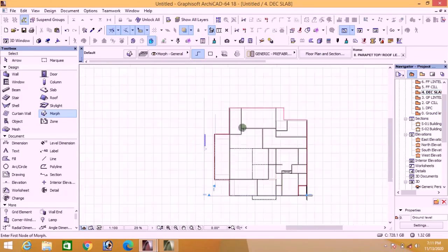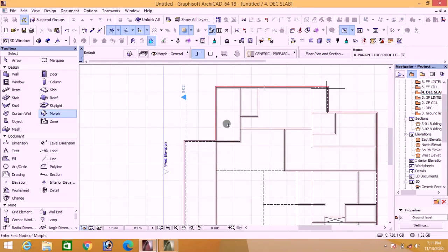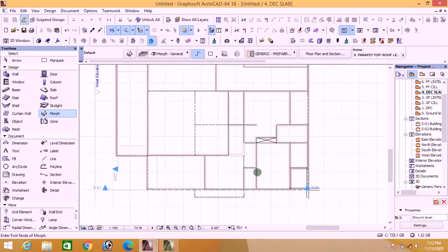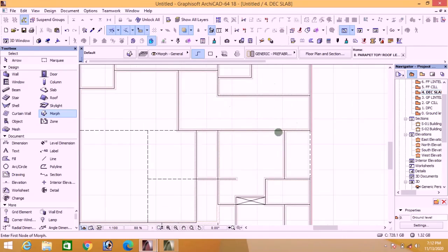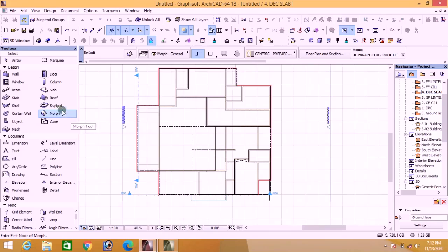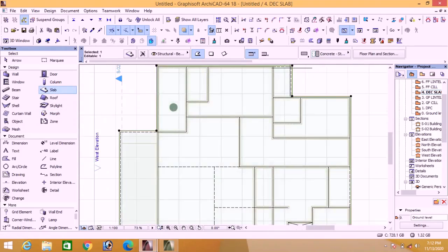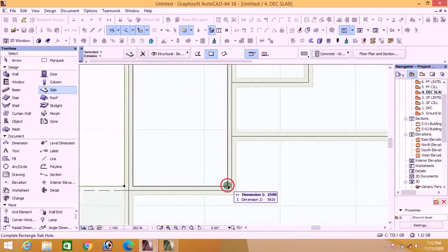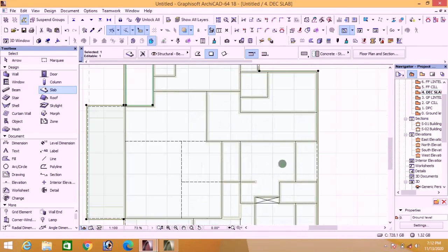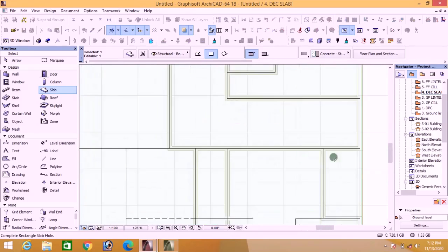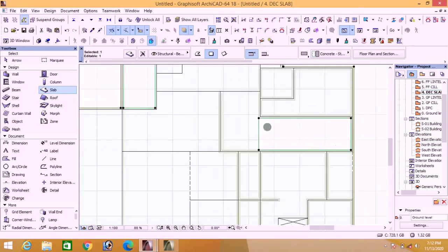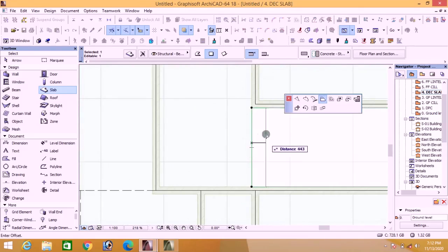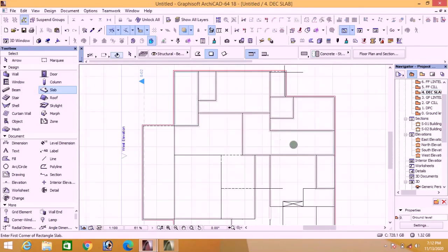We also cut this place open because what we have here is the stairwell. This is your staircase, so you have to cut this place open for the construction of our staircase. So click on slab, highlight this slab, change it to rectangular selection and pick it to this spot. It's now open for your stair. Stop here. So we have it open and we can drag this one further. This level. Beautiful. This is the stairwell of this place.